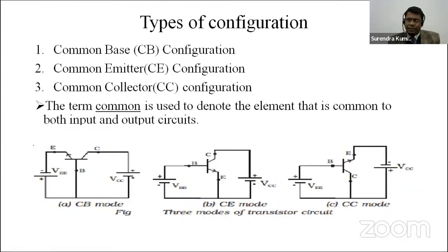In terms of output characteristics, the common collector is almost equal to common emitter mode. The output characteristics of common collector and common emitter configuration both are almost the same. Current amplification factor is almost the same. The change is the voltage gain. The voltage gain in common collector configuration is equal to unity. So there is no voltage gain, and it cannot be used as a voltage amplifier.